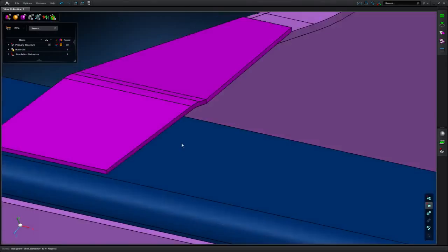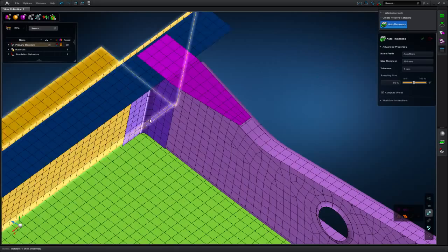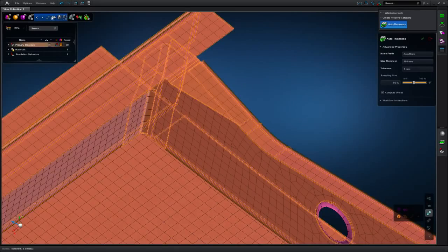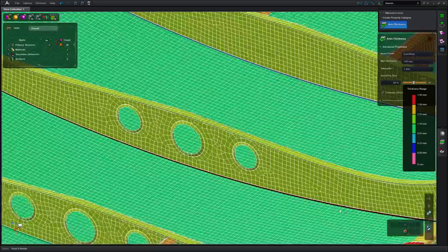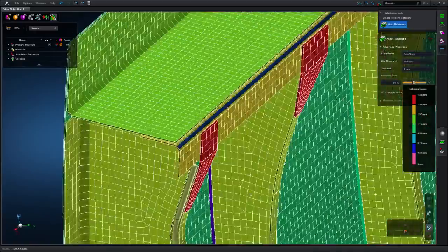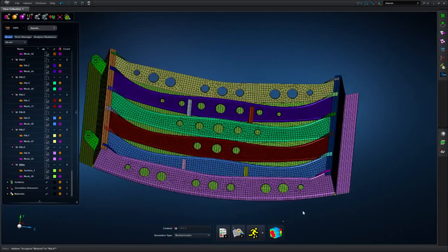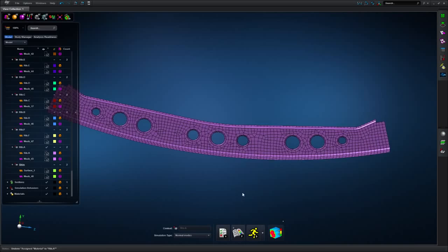If we refer back to the original solid model, each part has a different thickness. Our resulting mesh model must reflect this. You would traditionally have to define and assign each thickness property one by one, but in MSC Apex, the process has been automated. I have meshed and applied material and section properties to this particular part.